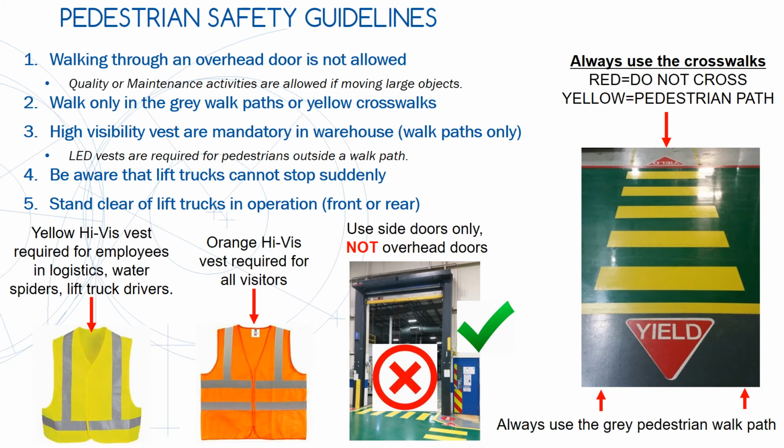LED vests are required for pedestrians outside of a walk path. Be aware that lift trucks cannot stop suddenly. Stand clear of lift trucks in operation, front or rear.